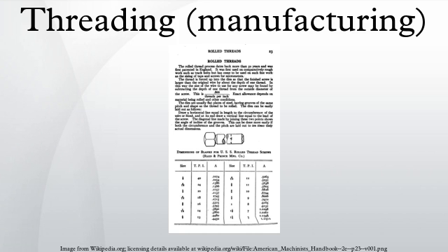This process is mainly used on threads larger than 1.5 in. It is commonly used to cut large lead or multiple lead threads. A similar variant using a multiple form cutter exists, in which the process completes the thread in one revolution around the blank. The cutter must be longer than the desired thread length. Using a multiple form cutter is faster than using a single form cutter, but it is limited to threads with a helix angle less than 3 degrees. It is also limited to blanks of a substantial diameter and no longer than 2 in.